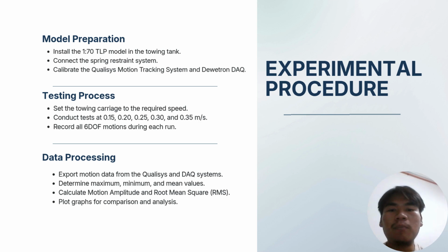So the experimental procedure starts with model preparation. Install the 1 to 70 TLP model in the towing tank, and then we connect the spring restraint system, and then calibrate the Qualisys motion tracking system and Dewetron DAQ.